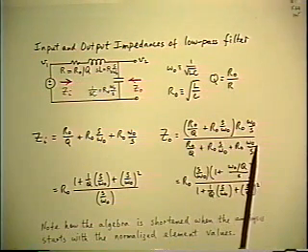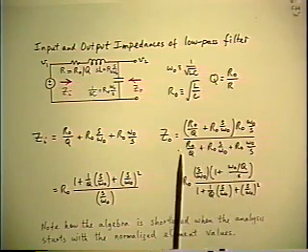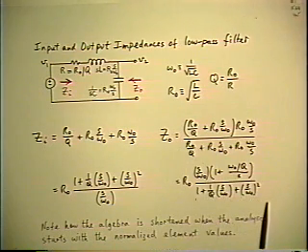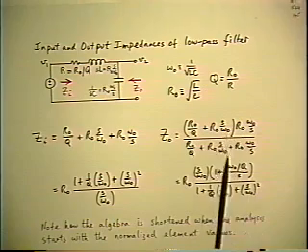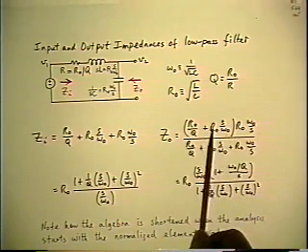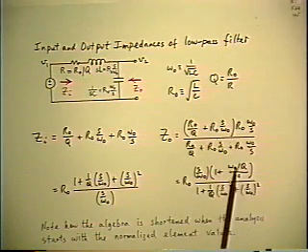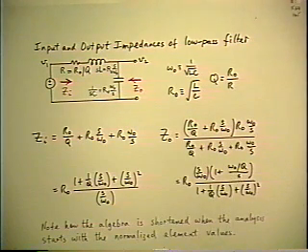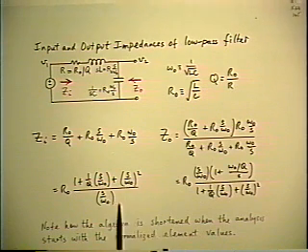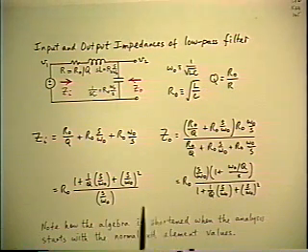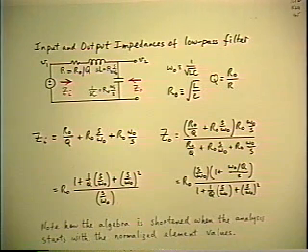Bring the omega 0 over s out front of the quadratic and reconstitute again the identical quadratic. There's a new factor in the numerator, which immediately becomes an inverted 0, 1 plus omega 0 over Q over s. So very quickly you build the pole zero forms for these other 2 quantities that you're interested in, input and output impedance.